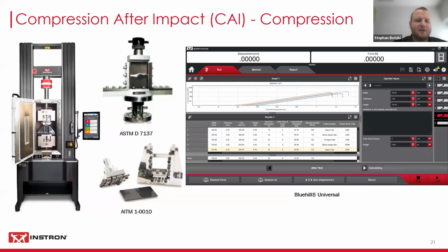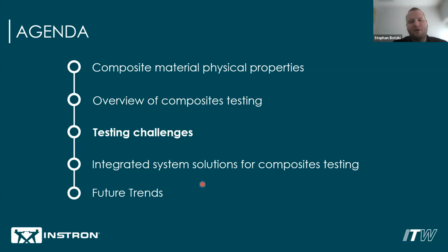So you can do this on a tensile tester. Like here, in this setup, we have an environmental chamber. So our grips are being extended into the chamber, and onto the grips we have compression platens mounted, a spherical one on the top, a fixed one on the bottom. We put our fixture in between, and then we're going to compress this specimen in the fixture and find out about the force that is left in there.